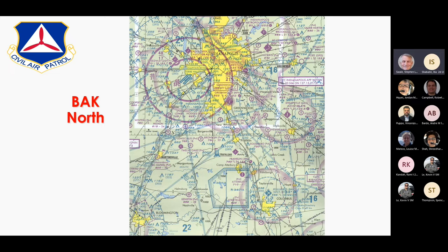Anybody flying an IR route may be a little higher. Typically, those might be flown at 1,000 feet AGL or sometimes a little lower. But the important thing on those instrument routes is with a lot of single seat airplanes, there'll be a flight of two airplanes. There'll be a pilot flying with their hood up so they can't see what they're doing. A chase airplane will be flying next to them to look for VFR traffic. So you could have two airplanes flying at about 1,000 feet, paying attention to each other, and one guy not even being able to look at you.